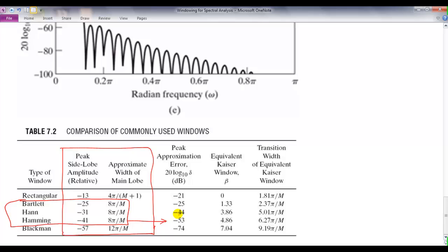It's a parameterized function, which is a function of two parameters. One figures out what is the relationship you want between the main lobe width and the side lobes, and the other determines the length. And in particular, if you turn this knob of the Kaiser window, it helps you go from rectangular to Blackman and all in between.